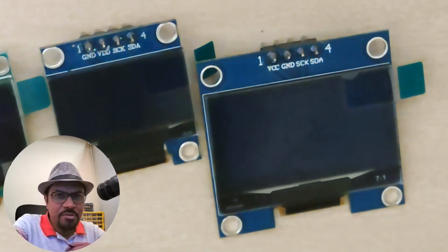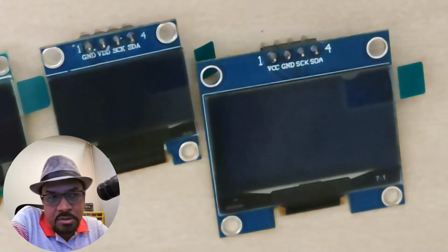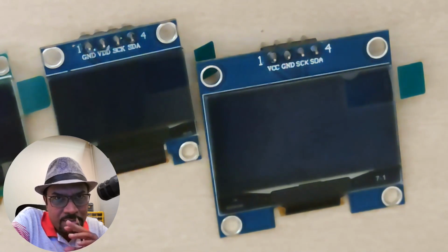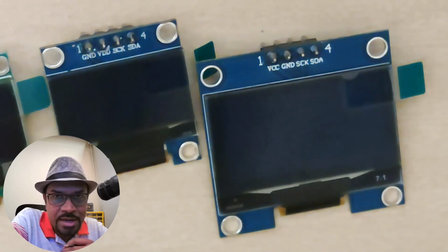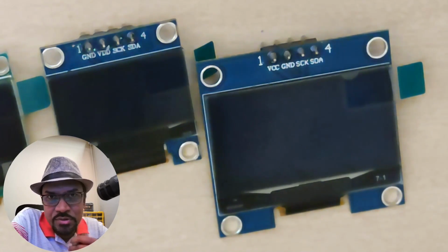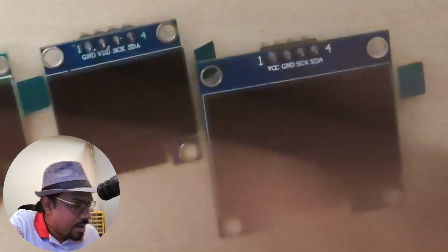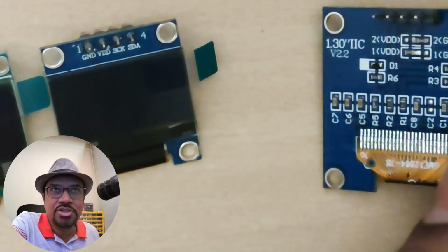If you're buying from online stores, I would recommend you to look up the description. So if I were to buy it from some credible online stores like robo.in or even RoboCraze, they actually provide the complete details about the technical specifications of the display. They might actually indicate whether it's a SH1106 or SSD1306 kind of display. They're actually documented. So you might want to make a note of that.